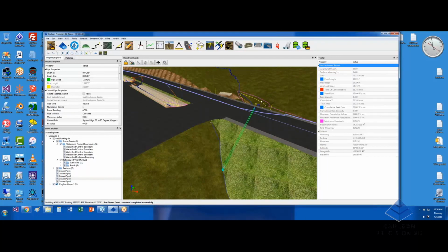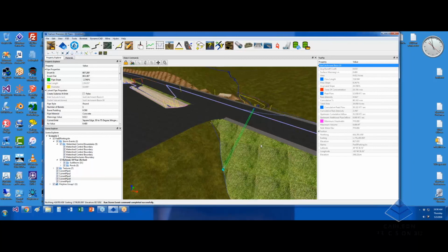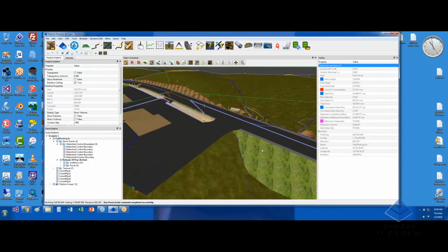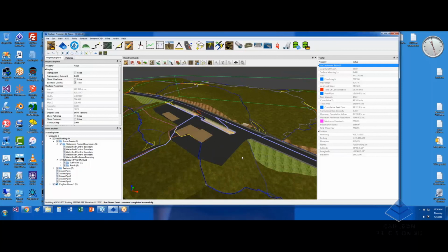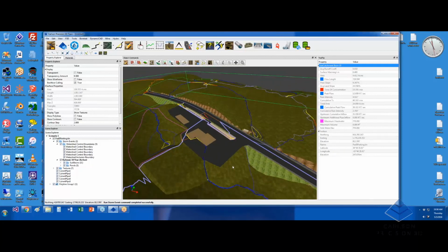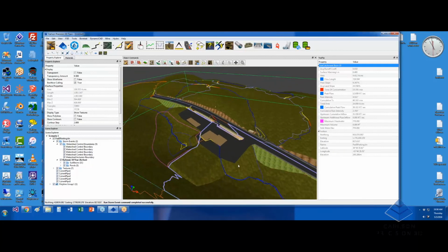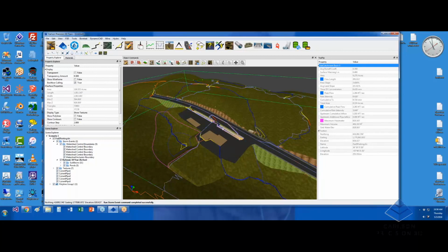So again, all of this was automatically taken care of and computed at this point, in which we can save all of this information back to CAD, plot the ponding, we can label it, we can bring all the culverts back in, all the head walls, and so forth for complete CAD documentation.